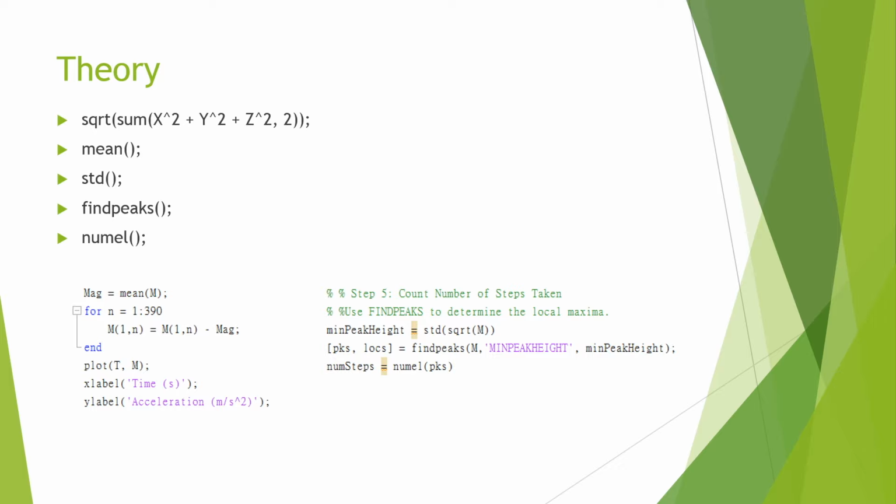Then we use the STD function to eliminate the noise of the signal. Finally, we use the FINDPEAKS and NUMEL functions to get the result of the footsteps.